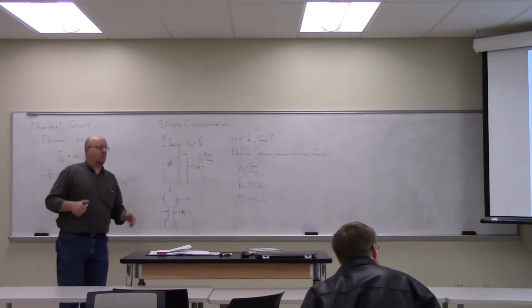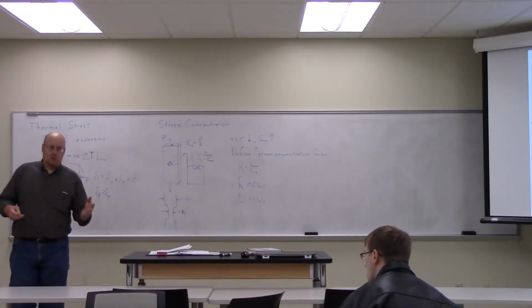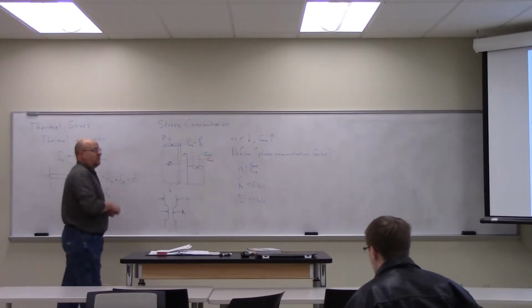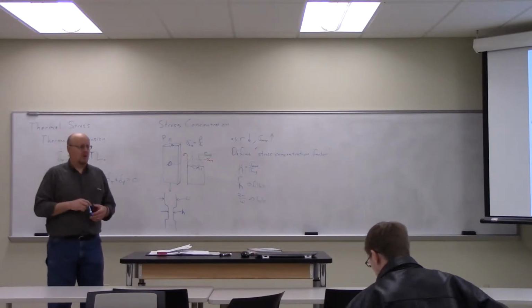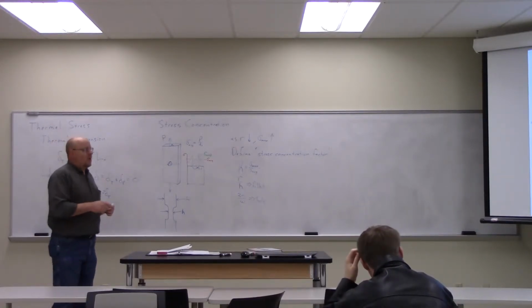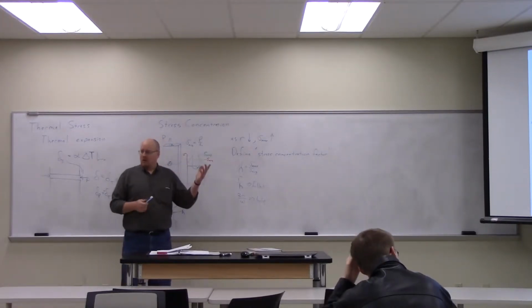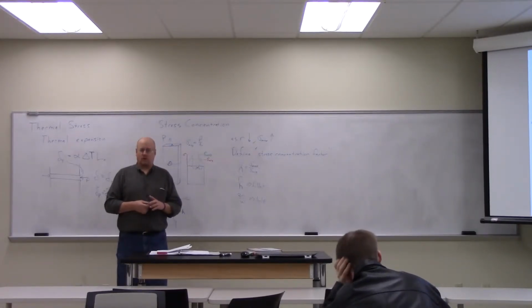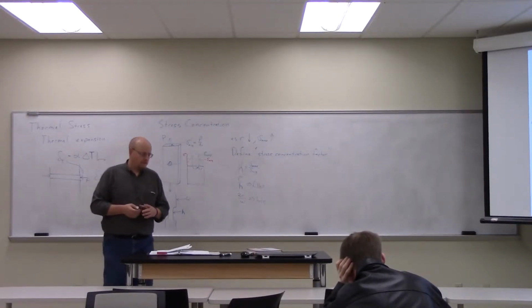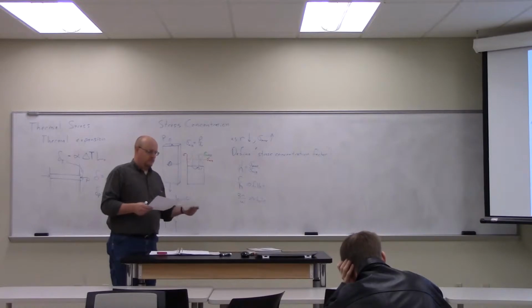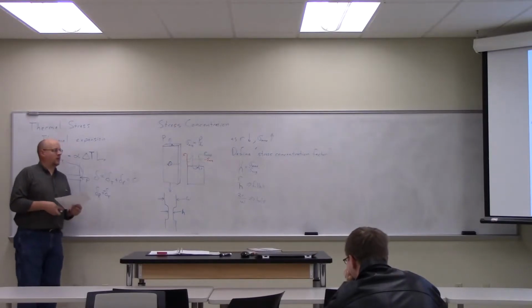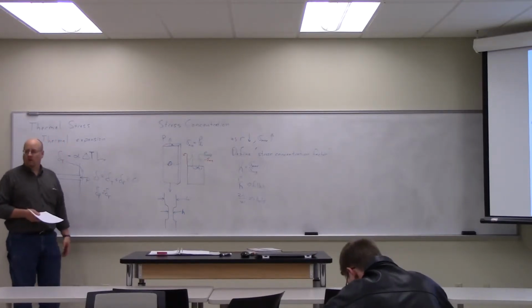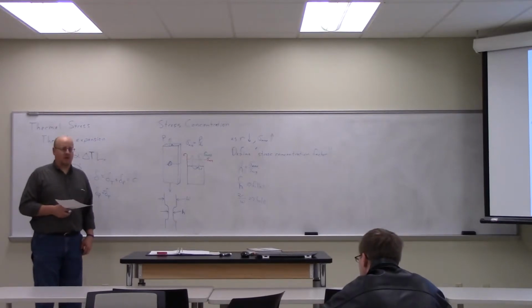These are just empirical values, at least as far as we're talking about in here. We're going to use these as empirical values. So literally, this table in your book, page 163, I think, if you've got this year's edition. I don't know what it is in the old edition. But that table is going to be the mechanism by which you calculate your stress concentration factors. For the time being, like I said, in a more advanced class, we can talk about it a little bit in material science, and then a little bit more if you ever took a graduate level course in mechanics of materials. Any questions?